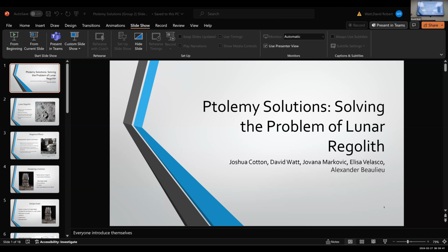So essentially, our target temperature inside the capsule is 5.4 Kelvin, and we need that so that we can maintain that 2000 pascals pressure within the bottom chamber, which we need to be around that area, because if it heats up too much and there's too much pressure, it